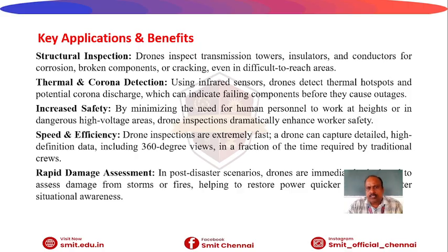Using infrared sensors, drones detect thermal hotspots and potential corona discharge, which can indicate failing components before they cause outages. It also increases safety by minimizing the need for human personnel to work at heights.